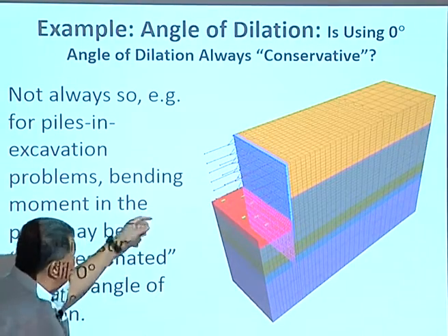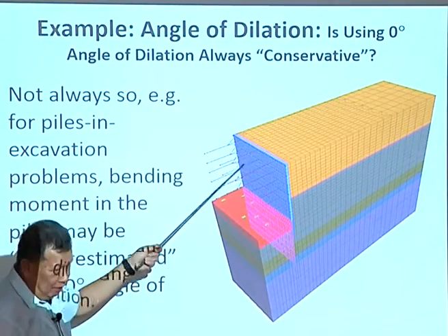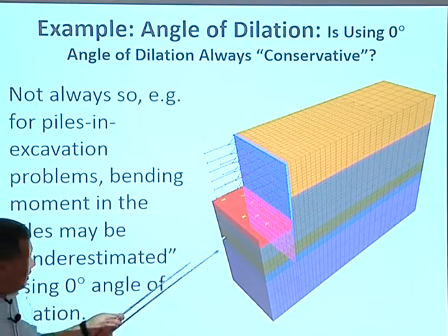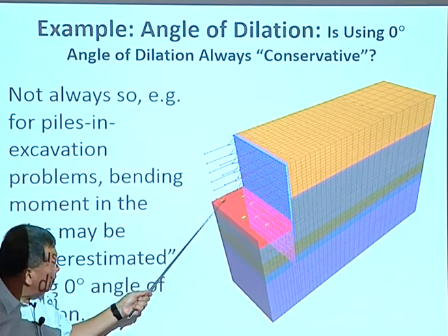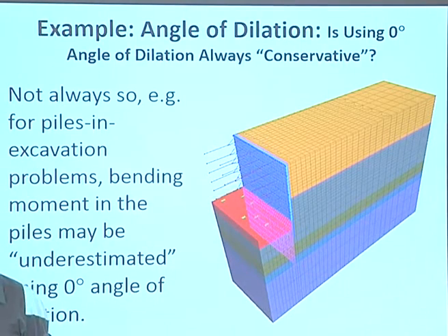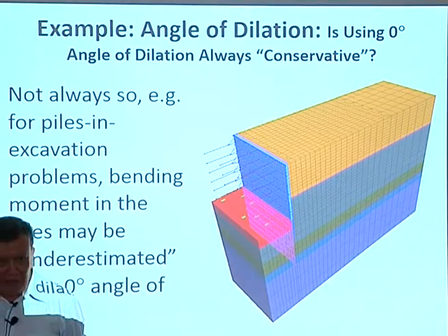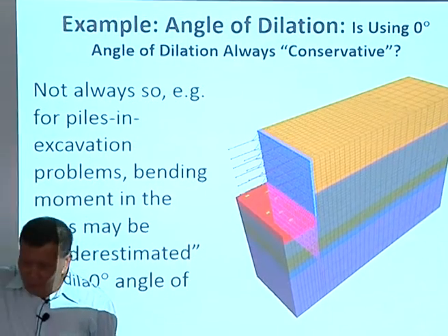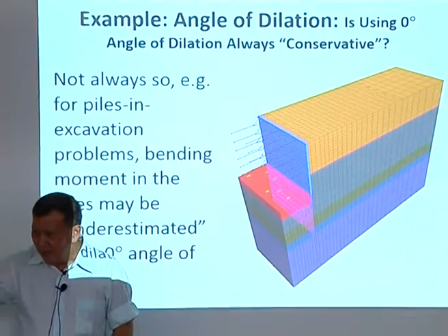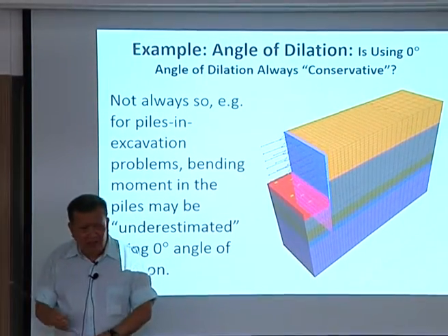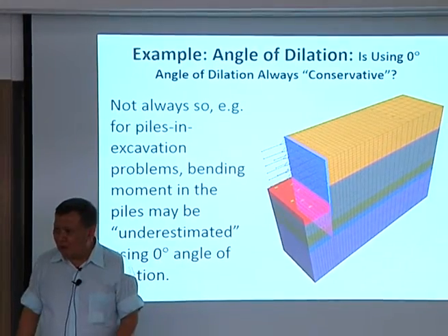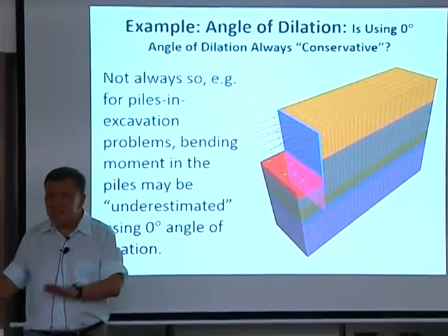You can see the struts and the chicken feet. These are what we call the chicken leg, or whatever you call it. Okay? And then inside the excavation, even before they do the excavation, they pre-install the pile inside. I don't know whether this is common in India. Have you done this? This is quite common in Singapore. Before they do excavation, they already put the pile inside. Then once they finish the excavation, they don't have to go down there and pile the thing. They just go and cast the base slab on top of the pile. So that's easy for them.